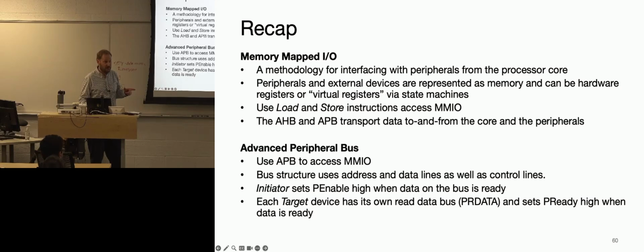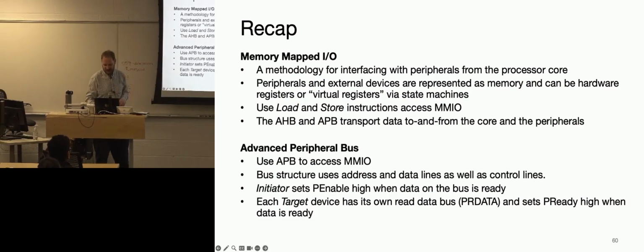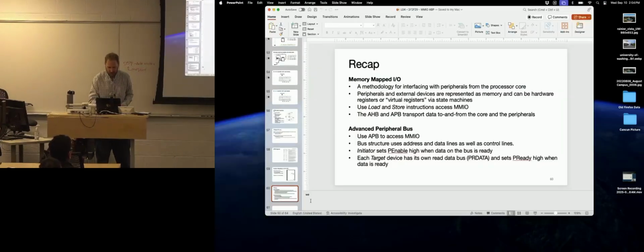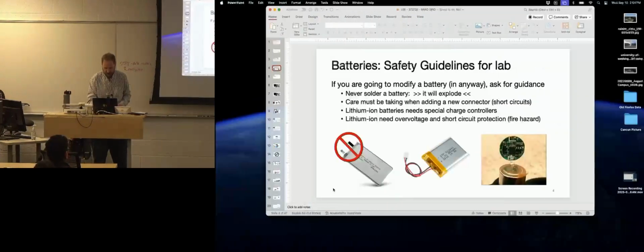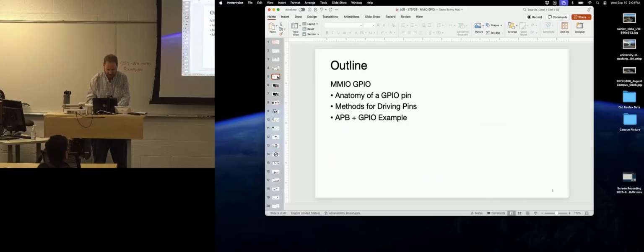Is the access phase only when P ready is high, and it has to be after the setup phase? Correct. Yep. So every interaction takes at least 2 clock cycles, right? Because you got to set up and then you got to have the access phase. All right. So here we're going to try and put it all together for you.